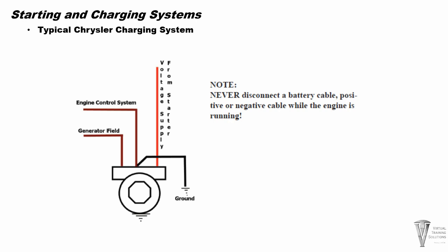The system target voltage is 13.5 to 14.7 volts. However, the actual voltage may go below this during heavy electrical loads and generator speeds. Also, the actual voltage can be lower than the target voltage between the battery and the battery voltage sense circuit. This will be approximately 0.2 to 0.3 volts.